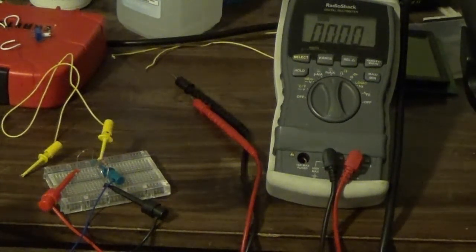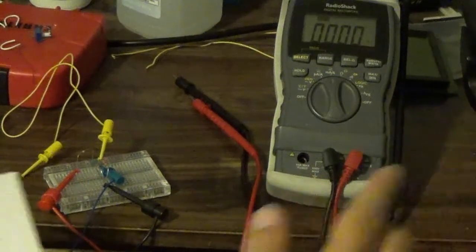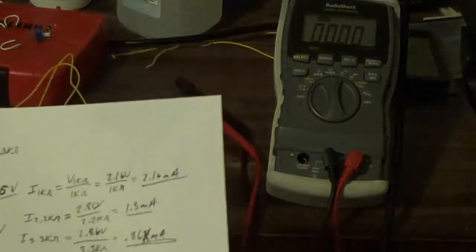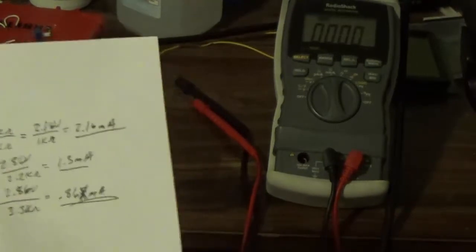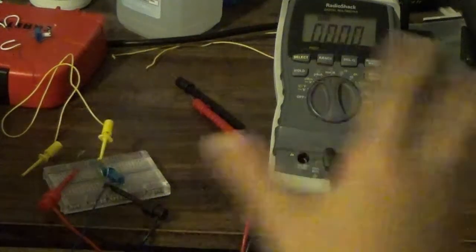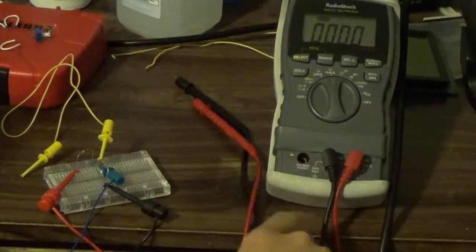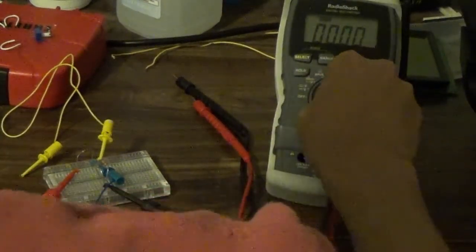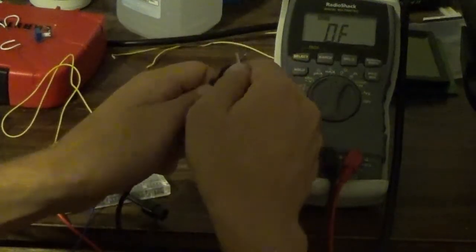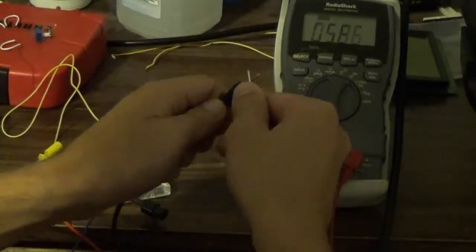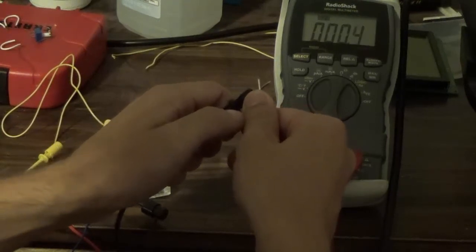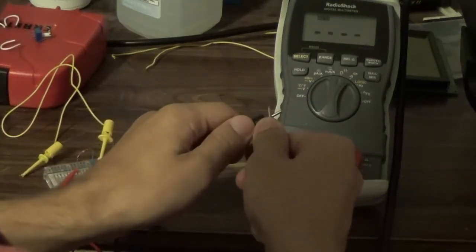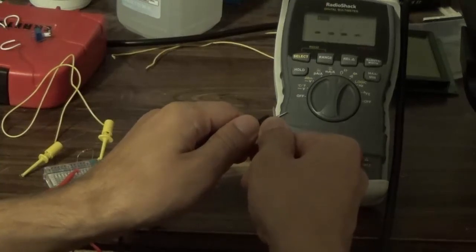I could probably dial it in a little more precisely and possibly target it right on 5 and maybe get even closer to that value. But I probably still won't get exactly 2.16. And the reason is because of, like I said, tolerances. The multimeter has a tolerance. The leads have a resistance. These leads, albeit they probably have a very low resistance, are a resistor. And these leads have a resistance, if this thing will tell me, of 0.4 ohms. Just trust me on that because it's being very slow in dialing in. But it said 0.4 ohms on there.